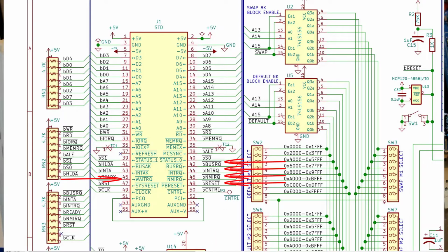The next 5 lines we are interested in, and they're implemented in this design, are the bus or interrupt requests. These 5 are all active low. They're all open collector. They all have onboard pull-up resistors to keep them non-asserted if they're unused or if the card is just being used alone on the bench without a backplane. So these 5 signals are on pin 45.